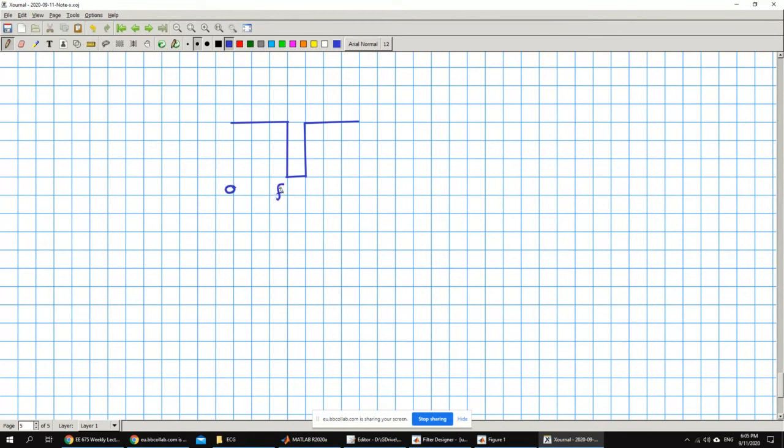This is F1, this is F2, and this is infinity. This is the maximum frequency, okay? So basically, you're passing your signal here, multiplied by 1, and attenuating your signal here, multiplied by near 0. And if you have the desired frequency that you would like to remove here, it will be removed. So what we can do is design a band stop filter,